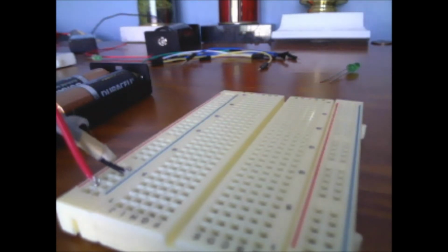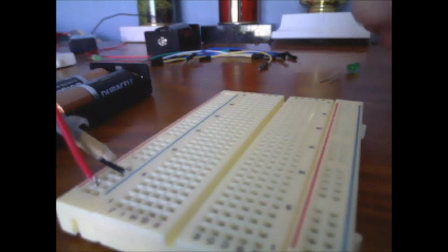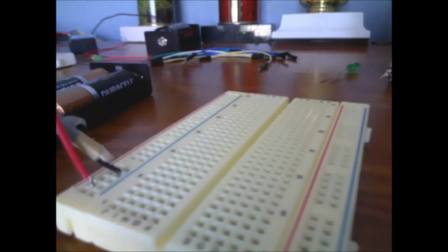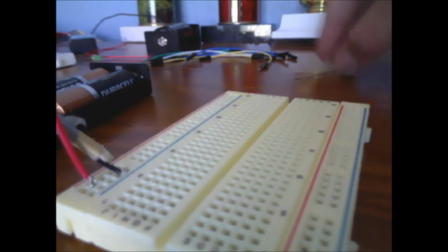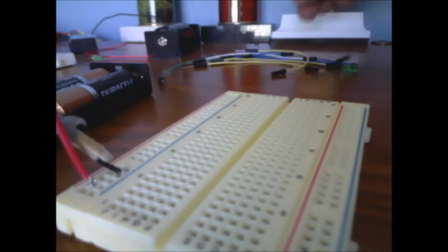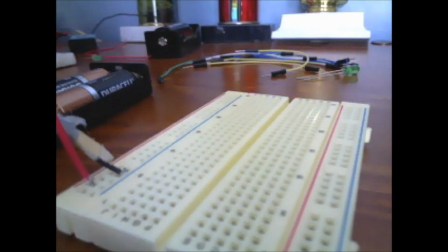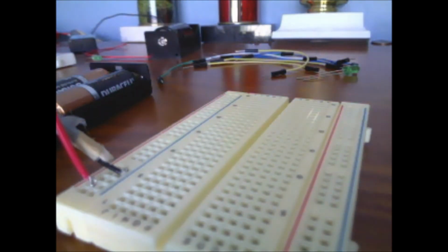So the first thing we're going to do, or let me just tell you what you're going to need. So you're going to need a potentiometer. This is a 10K potentiometer, which means it can resist up to 10K. A LED, I chose a green one. Some standard breadboard jumper wires, and you're also going to need a resistor for the LED. If you're using a 3-volt power supply, a good value would be anywhere between 50 and 100 ohms. I'm actually going to be using a 100 ohm resistor for mine. So let's set this up.